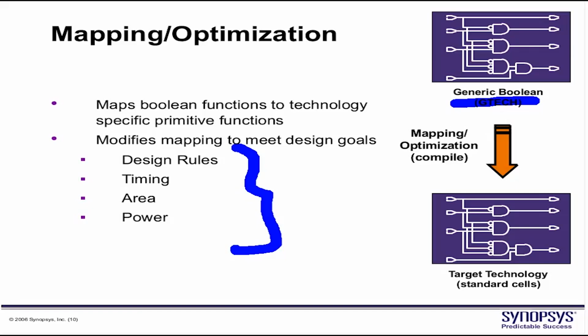If design rules are not met, the timing is not reliable. So for timing to be reliable, design rules have to be met first up. So this is the highest priority. This goes number 1. Timing goes number 2, because if timing is not met, it is not guaranteed that design will function correctly. Area goes number 3.